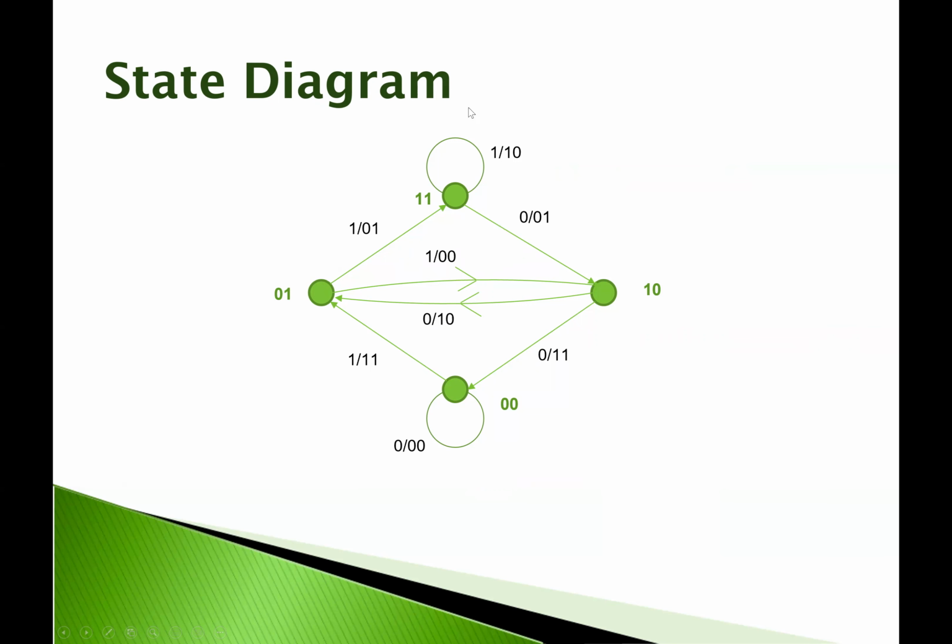Now, if we recall what we know about state diagrams, this first digit associated with these transition arcs is the input into the state machine. The two digits after the slash are the outputs, right? So the output bits. This is a code rate 1/2 code, so we'll have 2 bits output for each bit input. We could have a code rate 1/3.